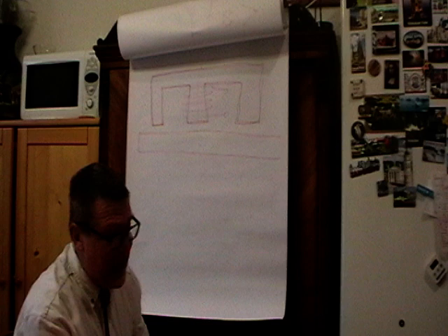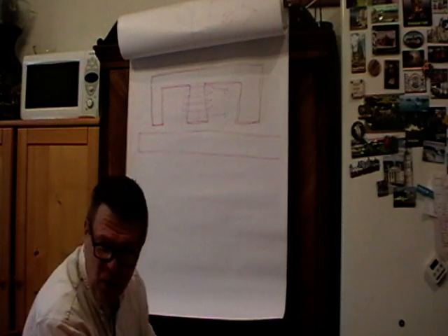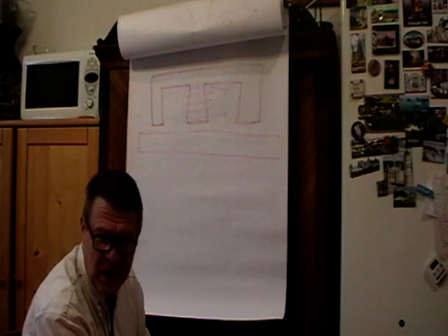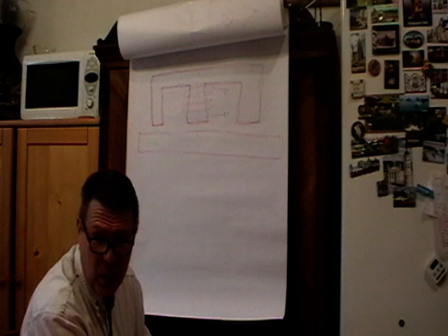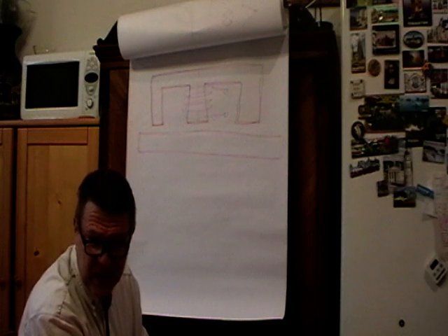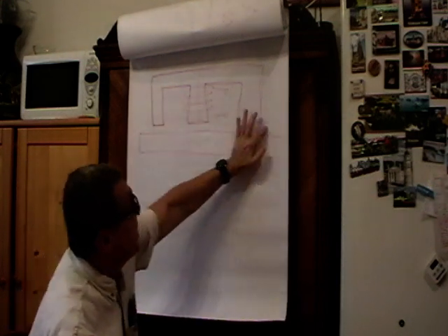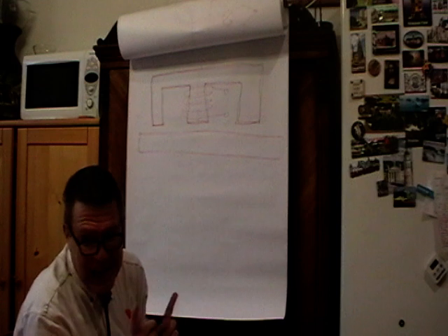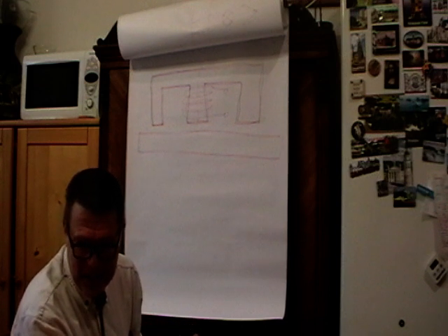As far as we have some interruption filled by air whose permeability is 1000 times smaller, the whole or most of the reluctance of the circuit is contained in the air gap here. And by the way, most of the energy of the magnetic field is contained in this gap.